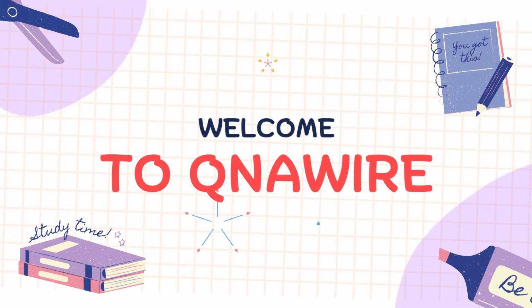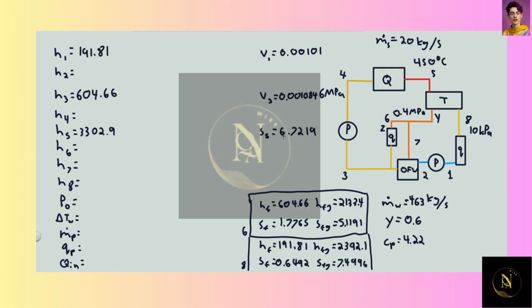Welcome to qnawire. In this problem, we're looking at a regeneration power plant with an added process heater that is taking steam from the turbine. Our water starts coming out of the condenser, going into the pump where it's being pumped up to 0.4 megapascals. It enters the open feedwater heater where it mixes with some of the steam from the turbine, and then exits as a saturated liquid, going into the second pump where it's pumped up to 6 megapascals.